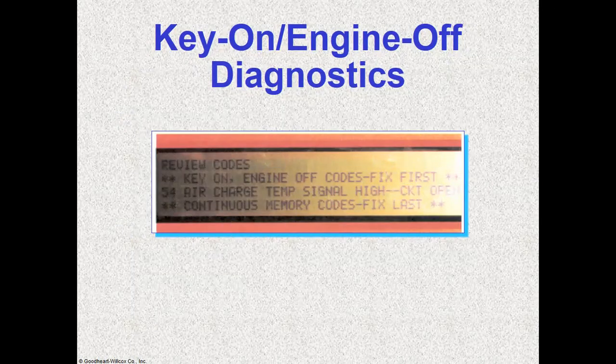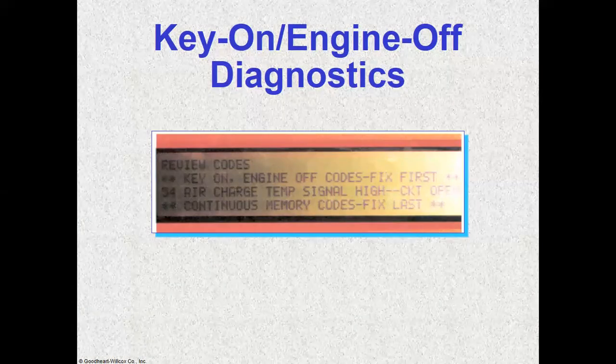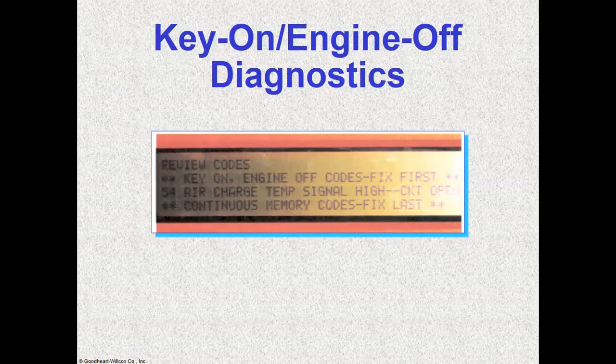Or sometimes you just want to see the values of certain sensors before you start to add heat, to see what drastic change happens after you start the car, so you can make a comparison between key off and while running.